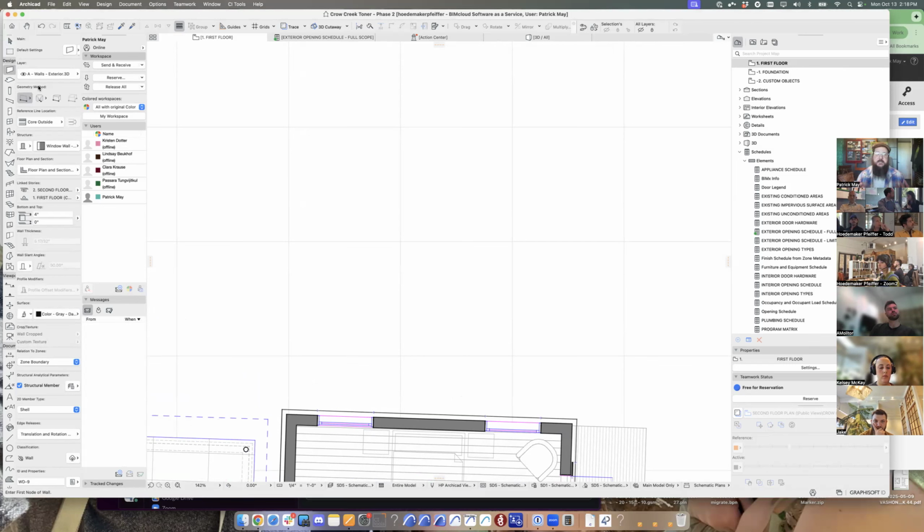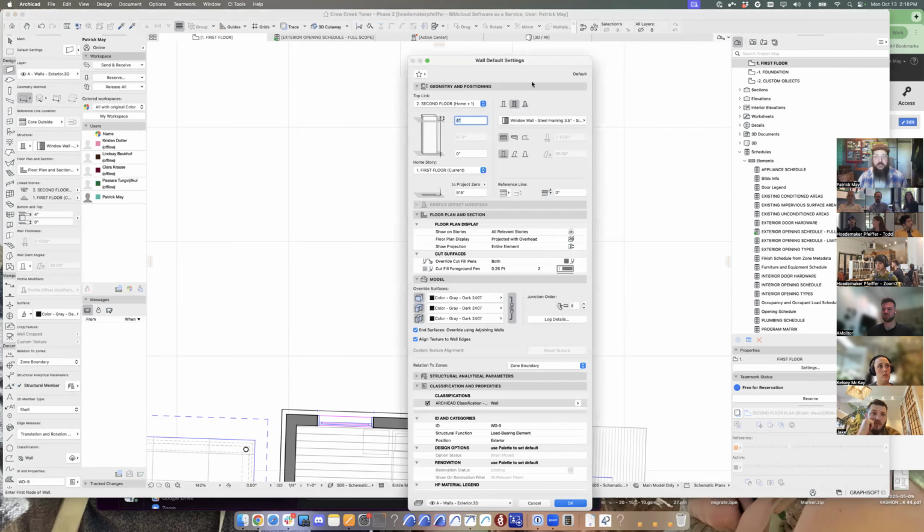In my mind, the most effective way is to start laying out spaces with actual walls, because those are going to be ultimately the tool that's going to define your rooms and your spaces, your volumes anyway. So even if it's not exactly what that wall is going to be, we're not worried about that. I'm just going to take any wall. The thing that I do want to pay attention to is this reference line. That reference line is the origin for that wall. The wall is an extrusion based on that vector.